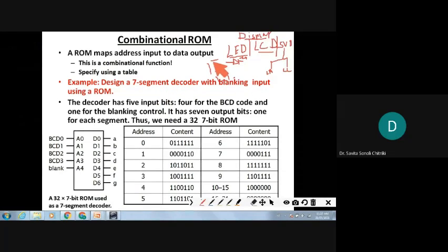Each segment will have one LED. That's what I had told. I had connected and shown also. So 7 LEDs will be there, 7 LEDs like this. If all the cathodes are connected common, and it has to be connected to negative for forward biasing, this is common cathode. So in common anode, what will be there? All the anodes are commonly connected and they will be activated.